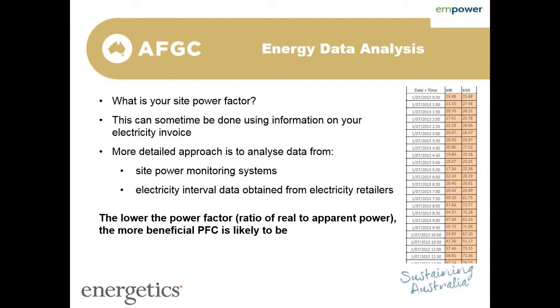It gives you an idea of your demand profile for your site. You can have a look and see whether there are any really big irregularities. You can also get average power factor, and power factor at those maximum demand events. So through the retailers is one avenue. You also may have power monitoring systems on site, depending on the complexity of your system. You may be able to just extract the data out of there in a similar format, and then have a look at it through Excel or some similar program.